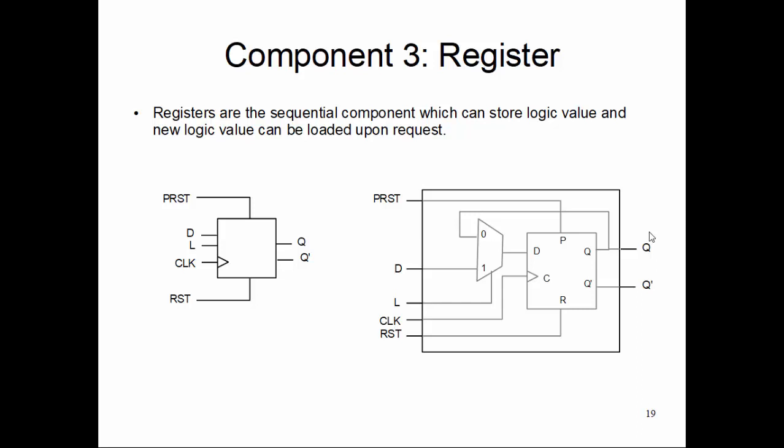So we need to build a selection capability in the storage, whether the incoming data is for me or not. Just think from the module B, C, or D perspective: some extra signal needs to come into them in order to latch or load that data, otherwise it will not load it. So that's what we do through a register.